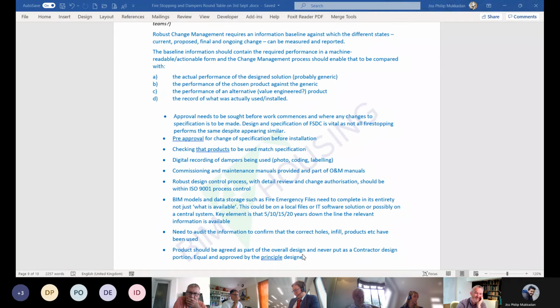We kind of need, I suppose, BIM to maybe help us with that, to say you can't mix this with that. So if in your model your original one says it's damper X and the hole size needs to be Y, then if you get damper C and the hole size needs to be size E, are those two at least compatible before you start? And that's your change management: how do you stop things just being changed just by being changed? Is there any security we can build into that to say, oh, hang on, you can't put that in this because there's not going to be a big enough hole? Or validation, really, validation of the new decision.